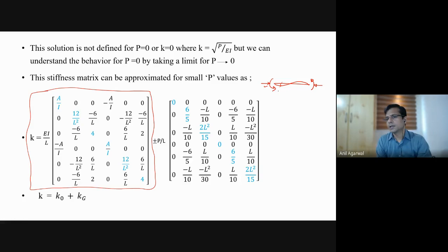But because of these deformations that you can see here, and P acting, the deformations will be further increased because of the presence of P. Earlier we were assuming that this deformation is purely because of M. Lateral deformations are only because of M. But if P also starts to interact and produces secondary moments, it will further increase the deformation.